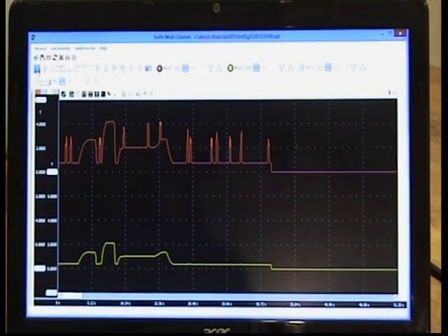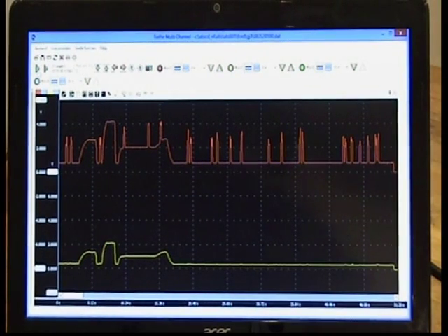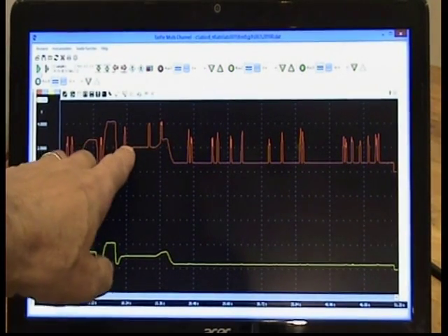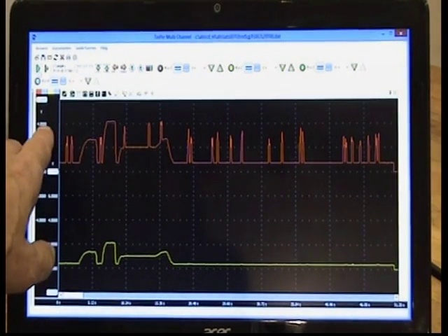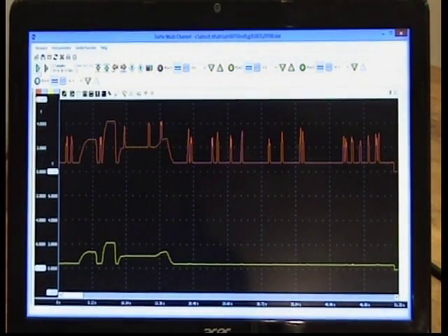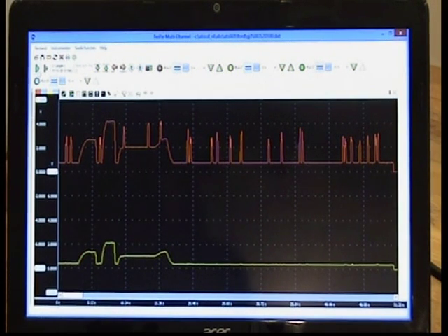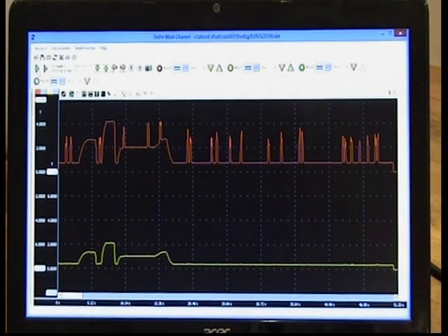Normally it can be a problem when you're seeing this kind of spikes on the signal. It goes up to 4 volts or sometimes not so high, but it cannot be a problem of the power supply of the track, of the potentiometer. It is also not a problem of the track itself, because then the signal voltage would go down. So maybe it has something to do with the ground wire of this potentiometer. So we are going to measure this ground wire and see what is happening there.